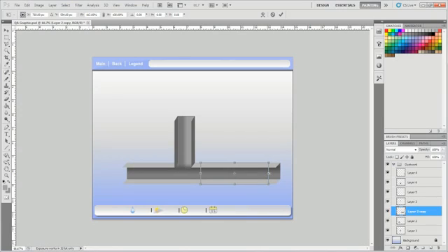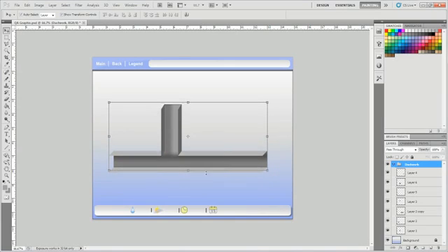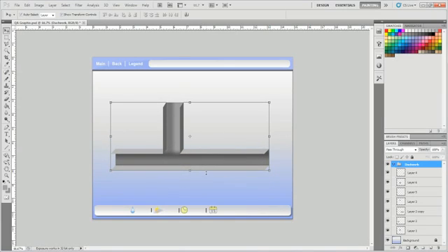To recenter the ductwork, you can select the folder in the layer window, then select the Move tool, and move it with the arrow keys. If you need to move longer distances more quickly, you can hold the Shift key down while pressing the arrows, and that will speed it up. Once your ductwork is where you want it to be, you should lock the folder so we don't accidentally move it when we place the sensors. To do this, you just select the folder, and once again, click on the lock button.